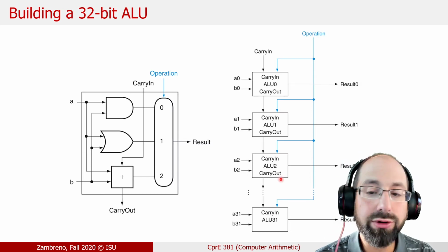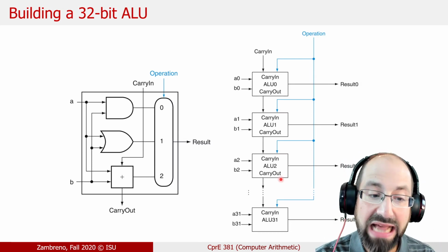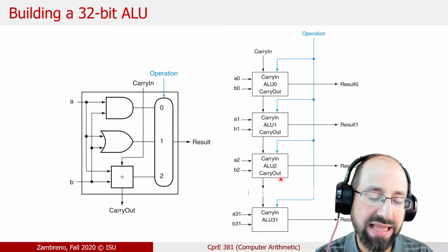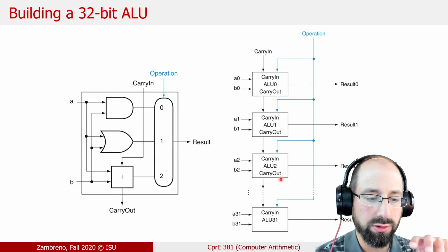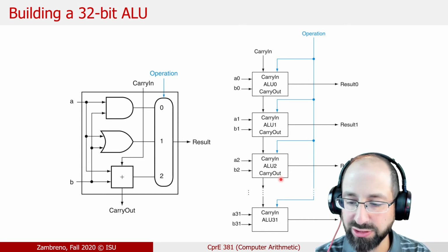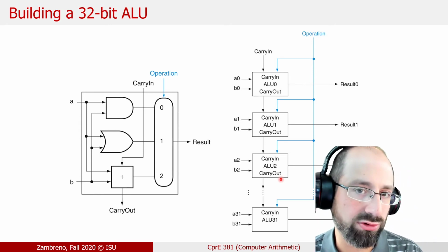Okay, so this general ripple carry design, this textbook design, is something we've already built, and it hasn't really changed. We built one that did add slash sub, and now the only difference as you move on to your project part A designs is that it's got that internal mux that's doing potentially more things. And the assignment specifies what those things are supposed to be.